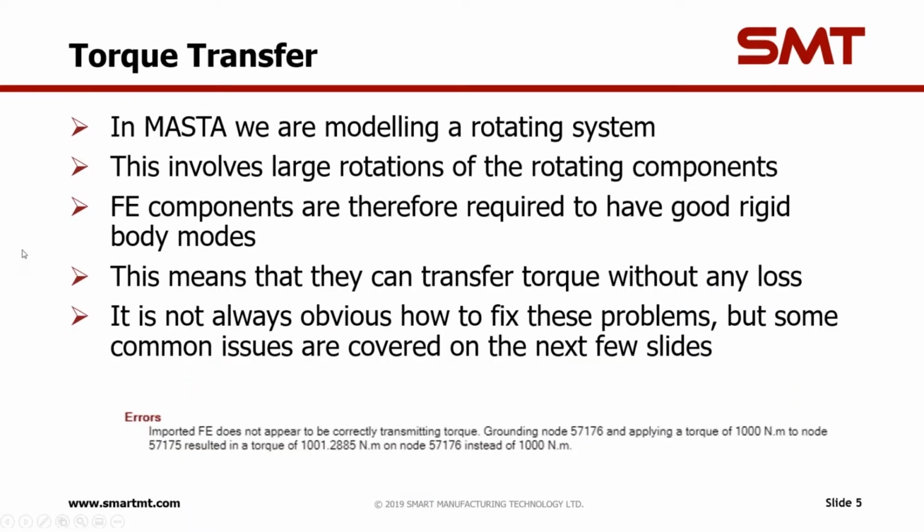So the next topic today is on torque transfer. Sometimes you might see errors such as this one shown below. You'll find your system deflection fails, and it'll give you some error about your imported FE not correctly transmitting torque, which is annoying. I'm just going to explain what that is and various ways we can check and fix that. First of all, to explain what the problem is.